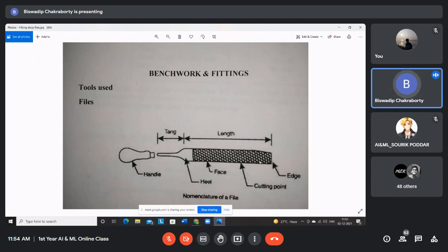These lines are kept at an angle so that when you rub the file against the raw material, these cutting edges are a little high compared to the surface of the face. I mean, strips of lines of very small height, but they are cutting.